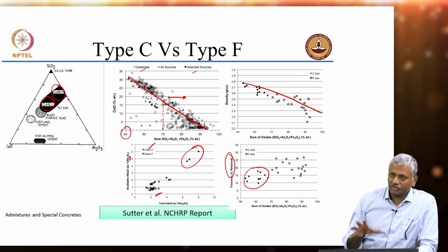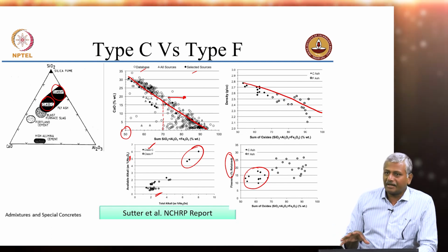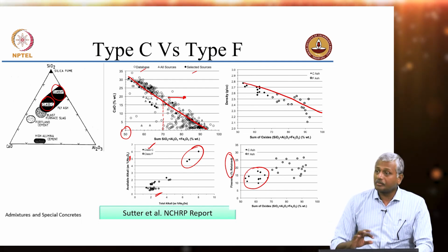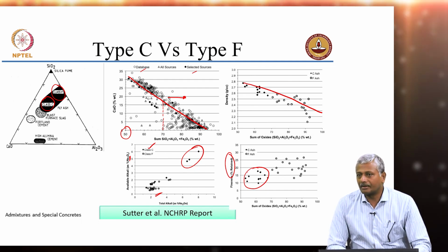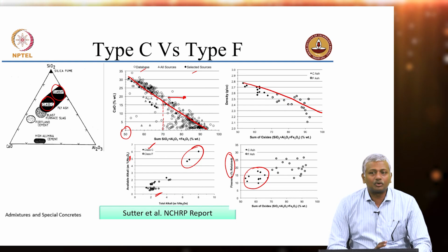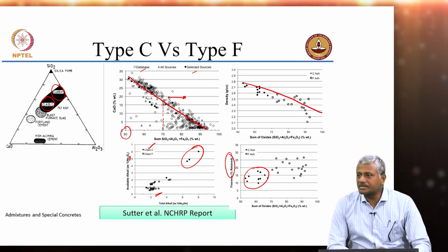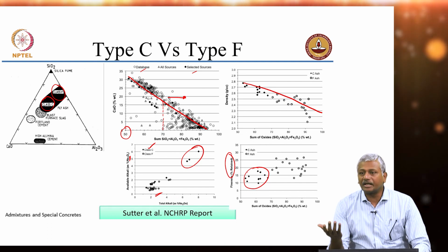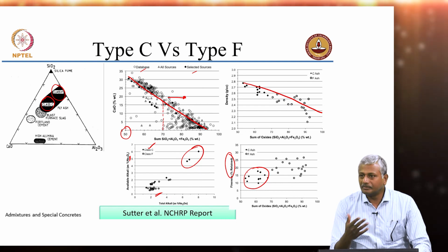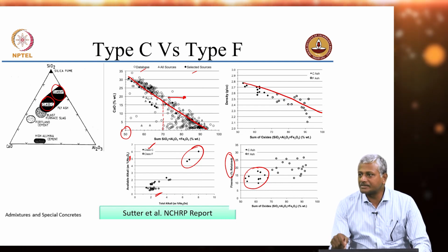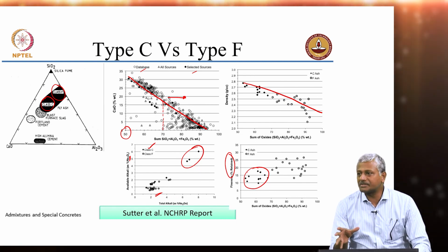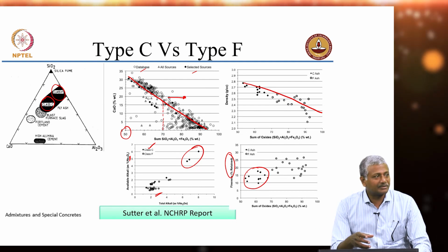So, the cement companies have to ensure that the net composition that they have for their PPCs is closely maintained, because they may be getting a type C or a type F fly ash or a mixture, and they are not very sure, right. So, again that leads to a slightly different kind of characteristic if you do not exactly know where your coal is coming from, because it turns out that shipping coal from Indonesia is cheaper than actually getting coal by road from Bihar or Jharkhand for a place which is on the port like Chennai, right. So, economics obviously drives the kind of material that you collect.